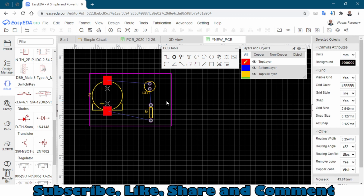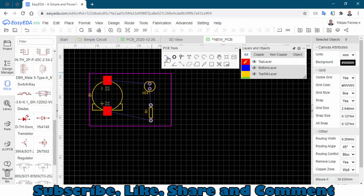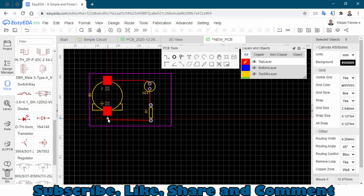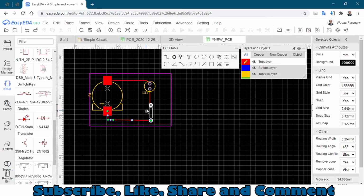and now we have to add the wires just by clicking on this icon, and from here we can add wires. You can also change the path of the wires, and you can also change the thickness if you want. And these are the through hole components.